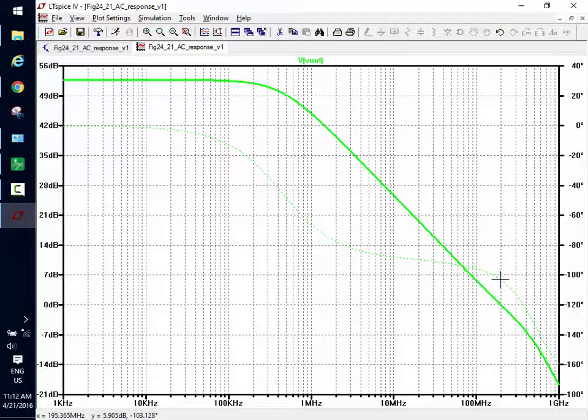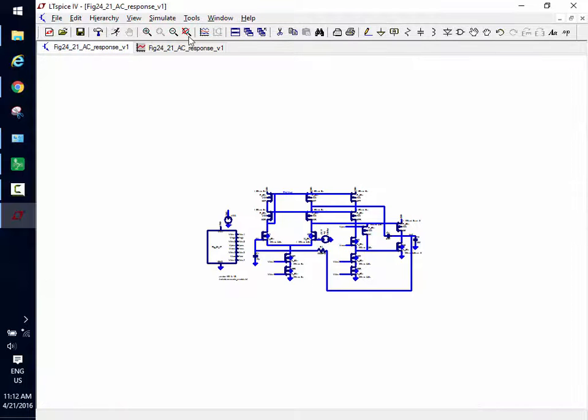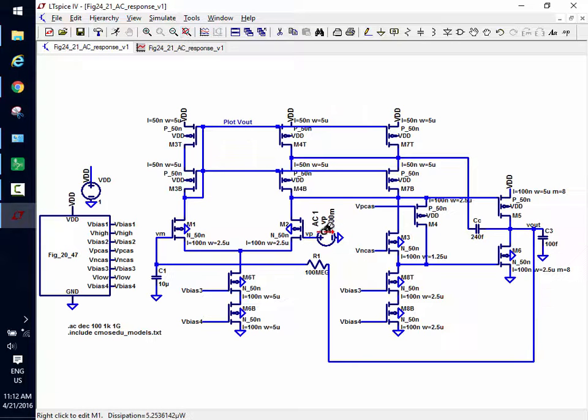Does everybody see that? Let's see what happens when, so how would I increase the gain further? Could adjust the gm of these a little bit. Remember I said we can do that? These a minor amount because they control both the unity gain frequency and the open circuit gain, etc. Let's go ahead and put this in a follower configuration.